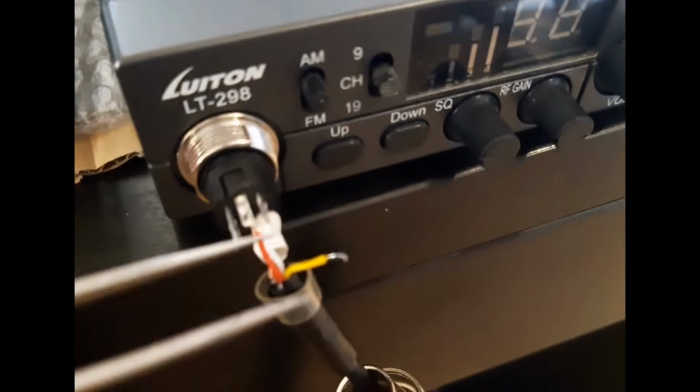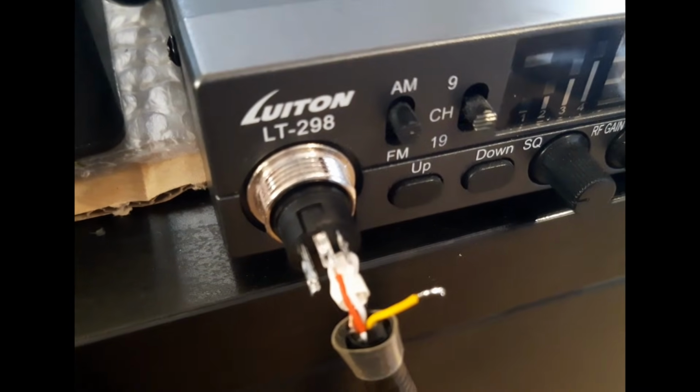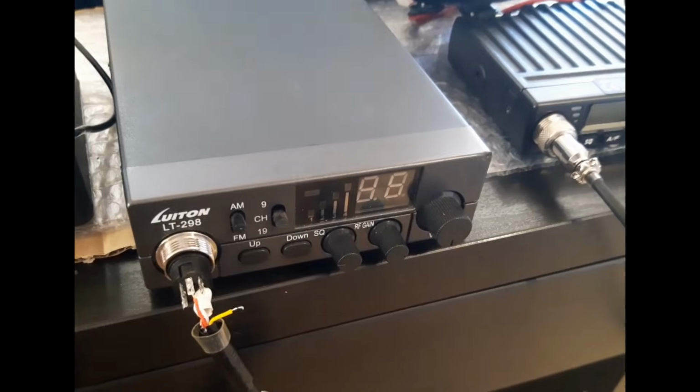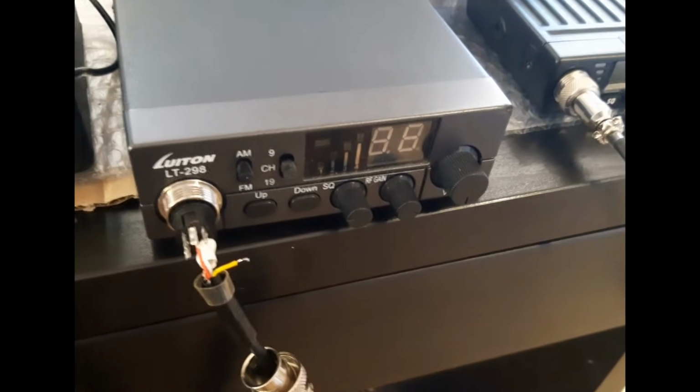However, some transceivers do not provide speaker audio through the front microphone connector, so newer versions of the interface include an additional cable that connects to the speaker output on the rear of the radio. If we use the rear audio connector, we must disconnect the corresponding audio wire from the front microphone connector and adapt the pinout to the particular CB radio or transceiver being used. That is why the wiring looks a little untidy here. We will clean it up later, after completing the remaining tests.